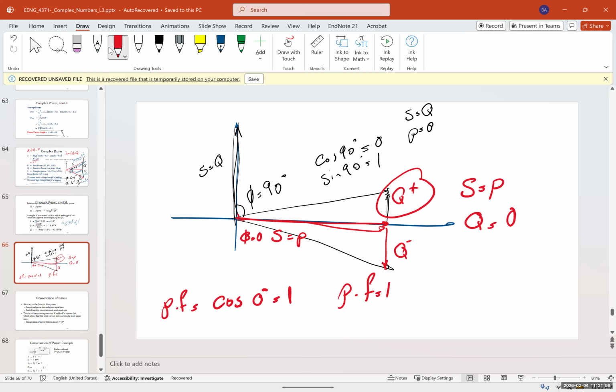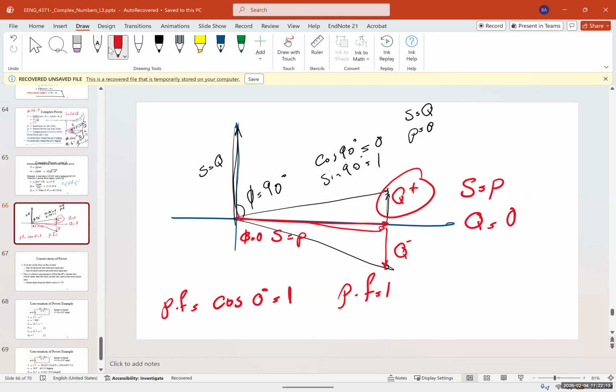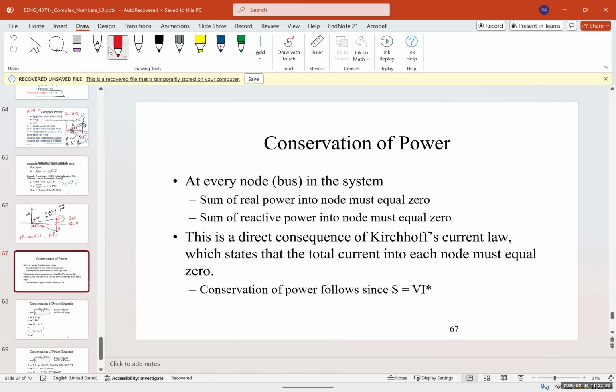You may have an HVAC where the capacitor doesn't work for a while, you won't notice it, but after a while the compressor is going to go out. So the problem, again, is long term: you're going to have a lot of loss and you're going to damage the system. That's the reason we put these capacitors. Usually in an AC motor, you can see there is a capacitor on it, which is a compensator for that.